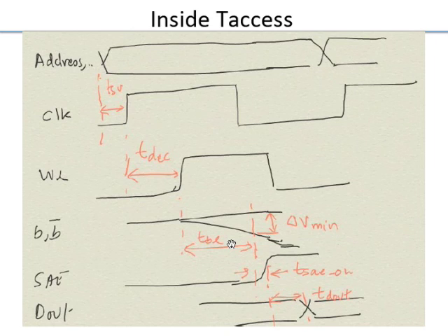What you can do is the cell itself. As I said, the delay is C delta V by I cell. Delta V is kind of defined by the offsets of your sense amp. So it's kind of hard to get below a certain value because, as I said, you have so many sense amps, and across process, voltage, temperature, you need to have good yields. Maybe 50 millivolts you can really push it down, but that's about it. Cell current: if you make the cell bigger, because transistors will be bigger, you'll have larger current, so delay will come down.